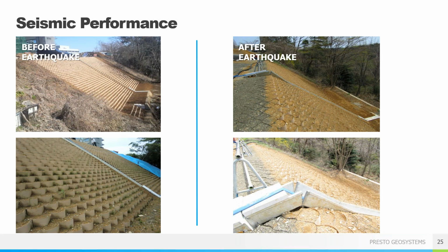Here you can just see a picture that shows, this is a reinforced slope. You're looking before the earthquake, where you had the GEOB on a 45-degree reinforced slope with geogrid tiebacks. You have reinforced concrete downshoots for the drainage from the parking lot. And you can see here after the tsunami and earthquakes went through, you had significant buckling of that concrete and displacement. The walls, since they're flexible, you can see actually moved and settled back into place, whereas the concrete had to be replaced and repaired.